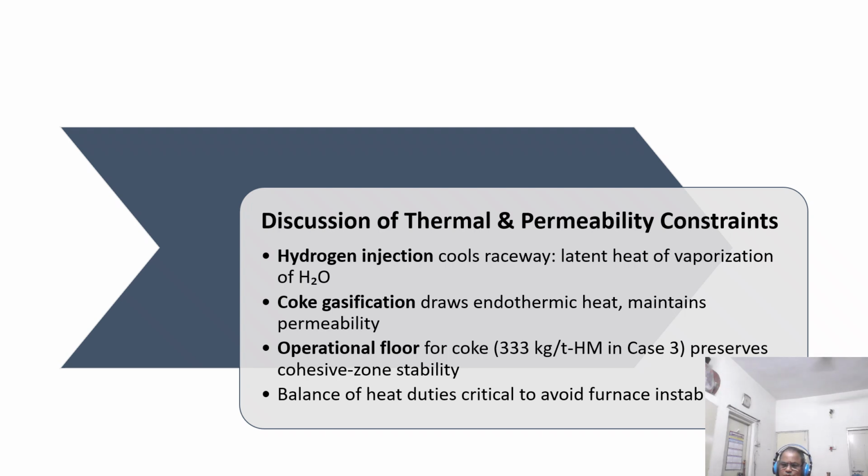So now let us explore the physics behind these constraints. When hydrogen burns, it forms water vapor which absorbs latent heat and cools the raceway. Coke, by contrast, not only fuels the furnace, it also maintains permeability and gas flow structure in the body.